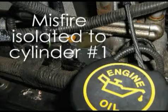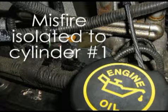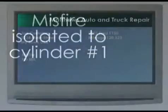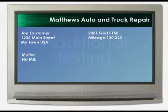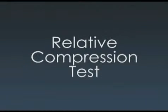Today seems to be a good day since the misfire turned out to be located on cylinder number 1 and it's easy to access. Being that this truck has lots of miles on it, we decide to go one step further and perform a compression test to make sure that there is no internal engine damage causing this misfire. Since we don't want to spend a lot of time on this, we will do a relative compression test. To do this, we disable the fuel system.